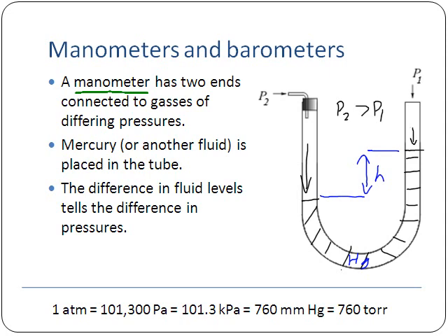So let's say that right now we find that we get a total of 12 millimeters difference in our two heights. If that's the case, then because P2 is greater than P1, I know that P2 has a pressure which is 12 millimeters of mercury higher than P1. To make this a little more concrete, let's say that we've got this at atmospheric pressure. We know we're at atmospheric pressure, which is 760 millimeters of mercury, so 760 millimeters of mercury is the pressure of P1.